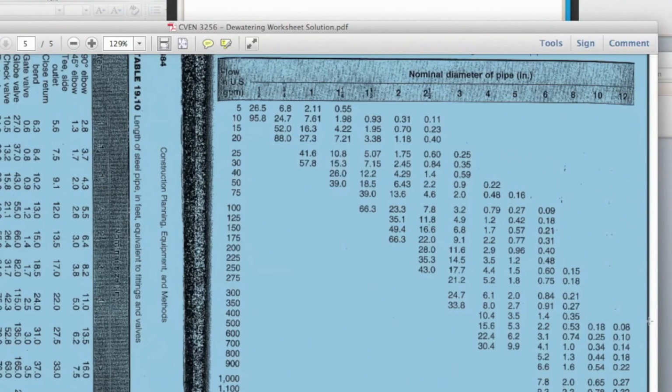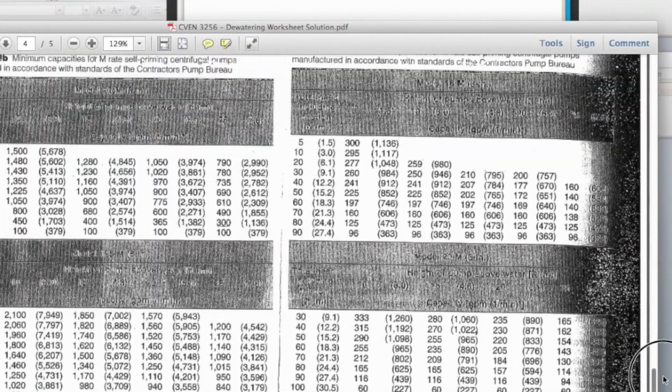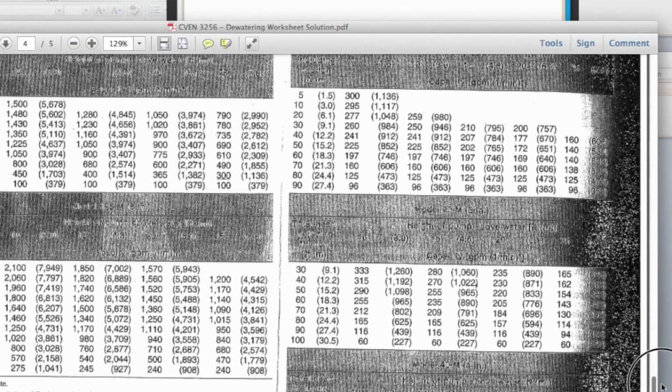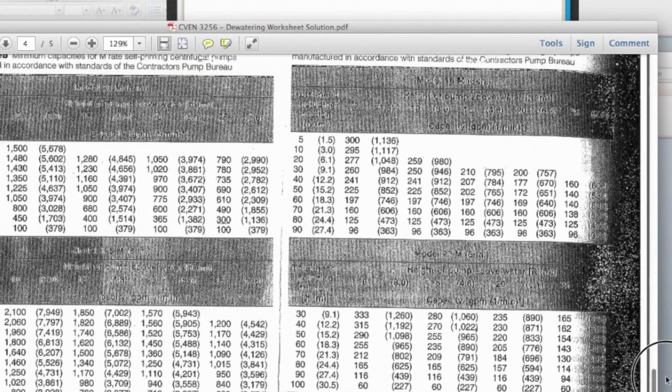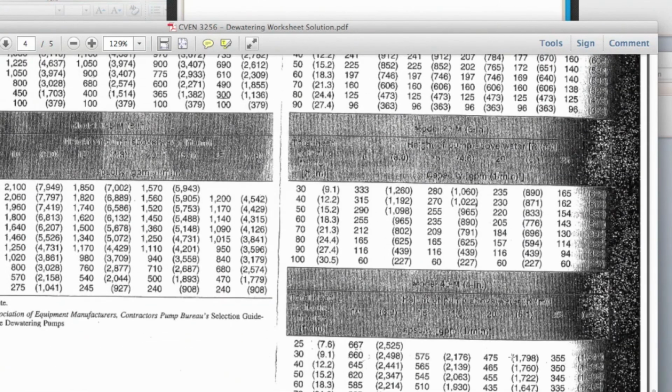Okay, so this table, here it is. There we go. We can look here for where the total head of 20 feet and the height from water of 10 feet gives us an allowable value. So coming over here, it would basically be here. That's plenty. That's even better. But those are probably more expensive. Let's look at the cheapest one that'll work.